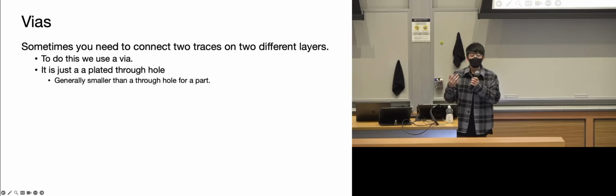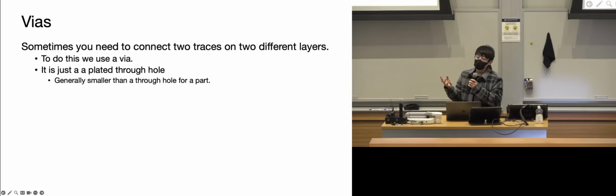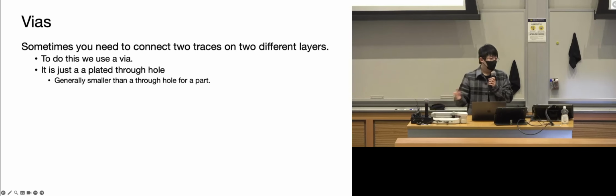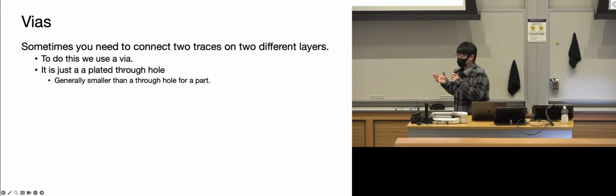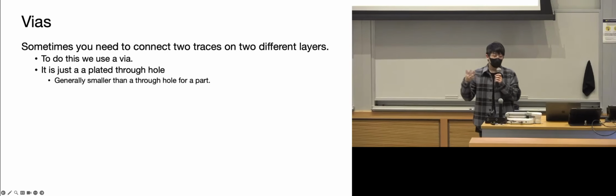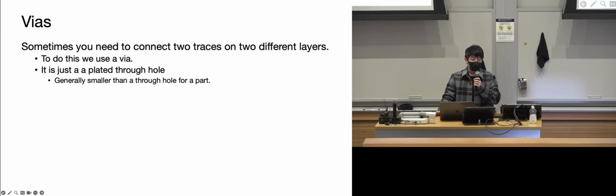naked via hole. Imagine each of these vias can be one of your nodes on your circuit. So if you want to know if this component is getting the right signal, etc., the vias can also serve as a good connecting point on the PCB board. So usually, if you're still doing iterations, you're not finalized on the PCB design, the first couple of versions you would probably have the via holes naked. For the final versions, obviously you will cover everything to just have better signal integrity in general.